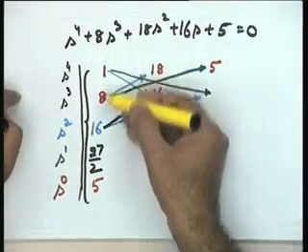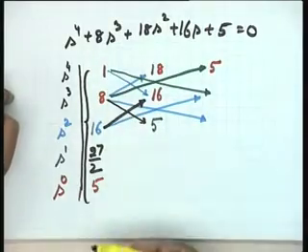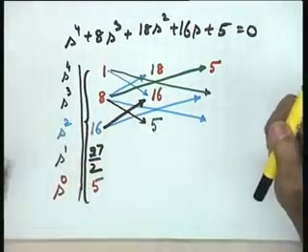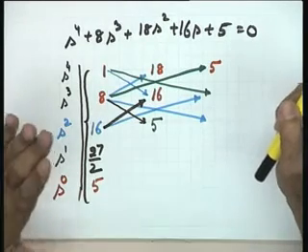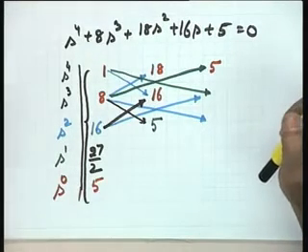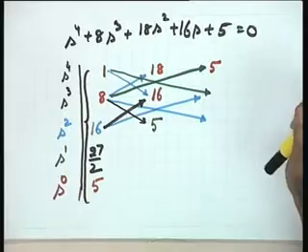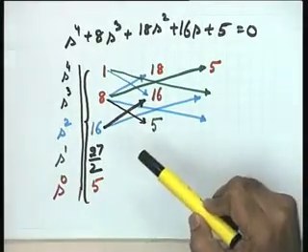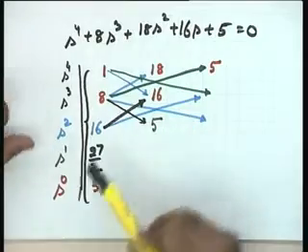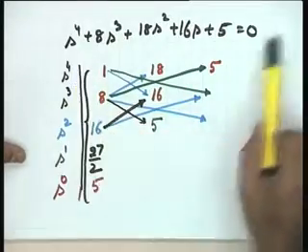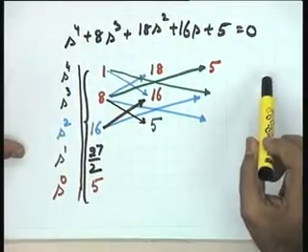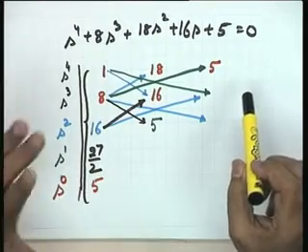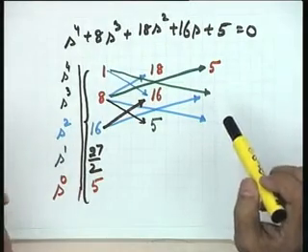So, if there is no change in the sign, if all the coefficients are positive, it is guaranteed that all the roots of the characteristic equation are in the left half plane and the system is stable. Please see, though in this particular case formulation of the Routh array even on computer is much easier than solving this equation, still I do not think the advantage lies in this aspect. The advantage lies in the design aspect, which will come later.